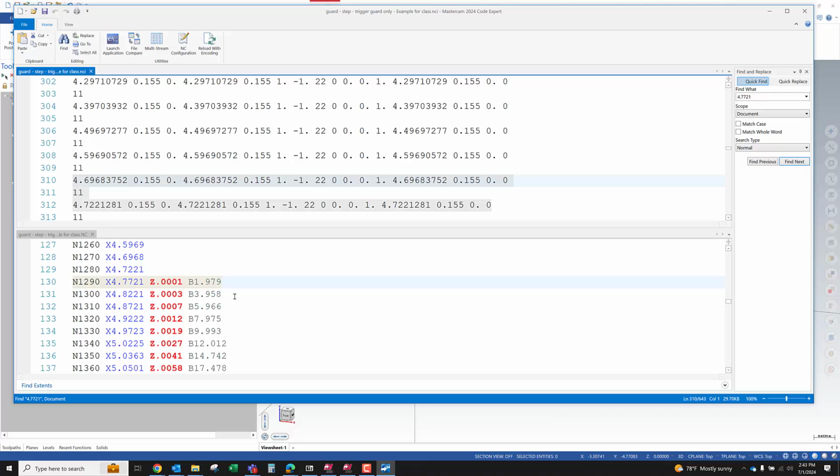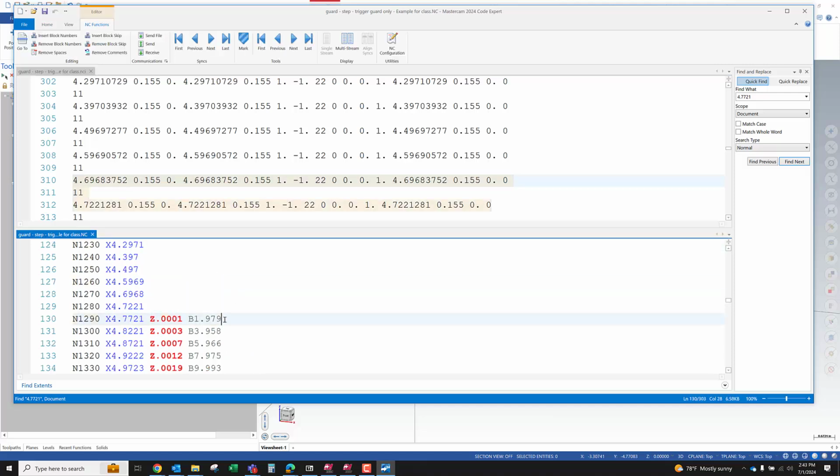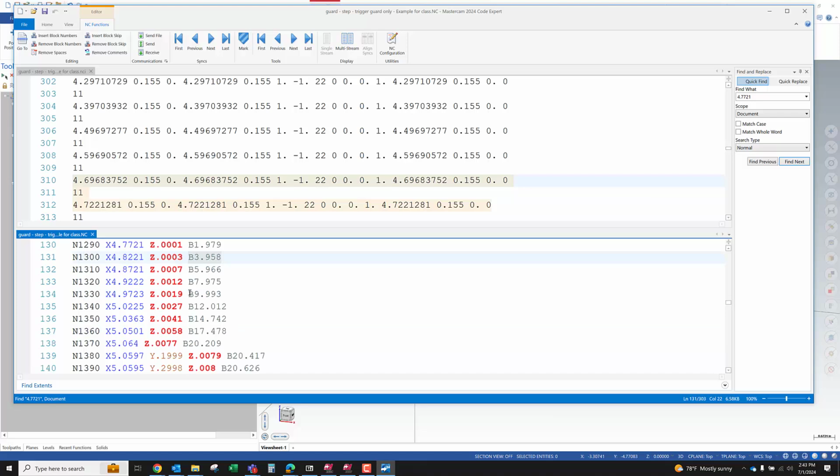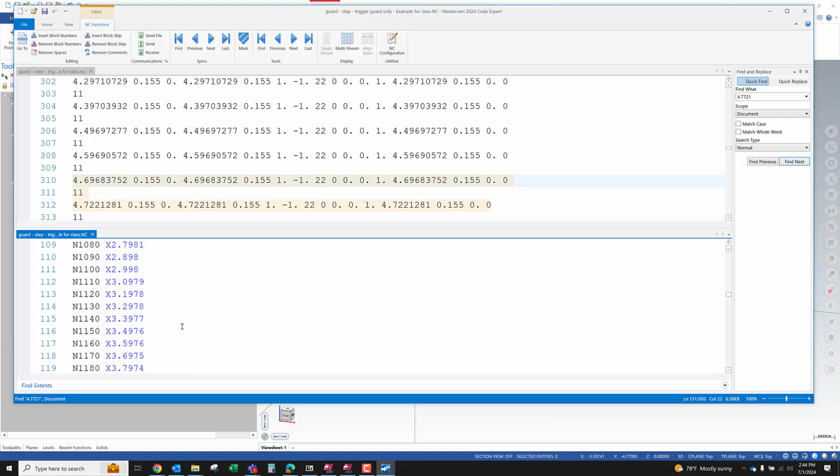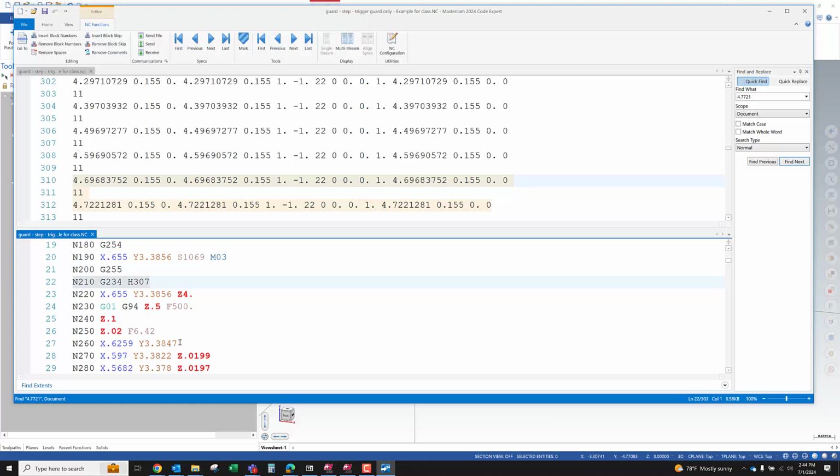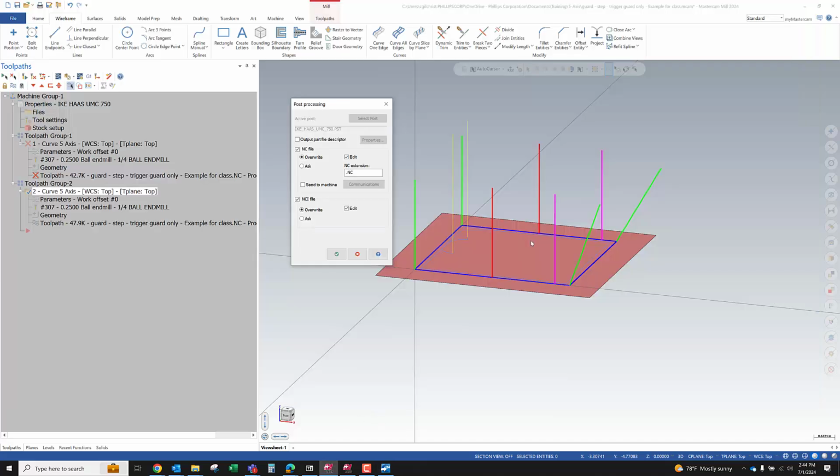It's that change in vector that's then going to get resolved to create this rotary angle output to actually rotate the machine. And because we're using dynamic work offset and tool center point control, the coordinates are actually a really close match to what the vectors actually look like.